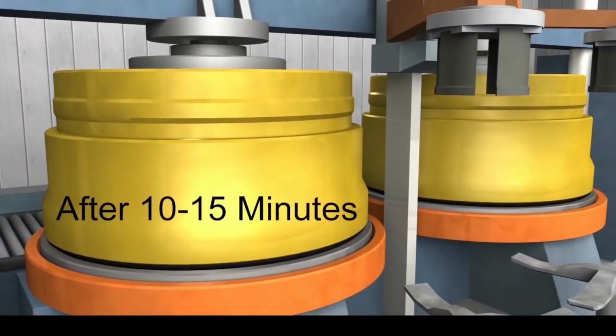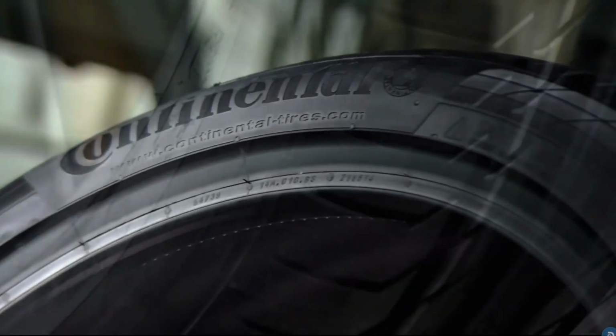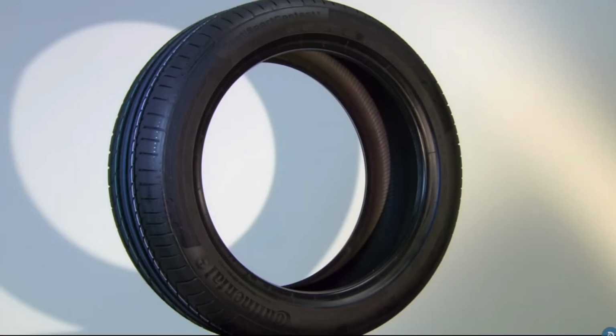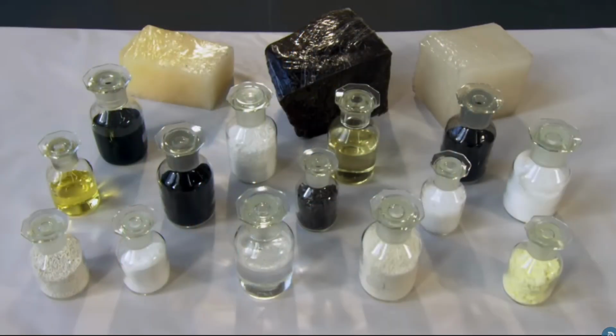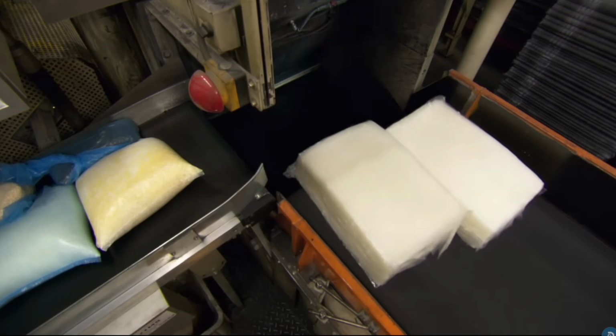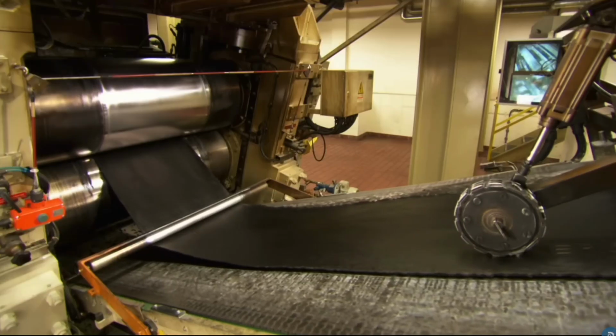Now, there are a few limitations to blow molding. One issue is that blow molding is not compatible with all plastics and rubber materials. For tire manufacturing specifically, only certain materials can undergo blow molding. Another issue is that blow molding is typically intended for lightweight and low-stress situations. This means that tires that undergo blow molding may not be suitable for heavy-duty situations, such as fitting for trucks or semis.